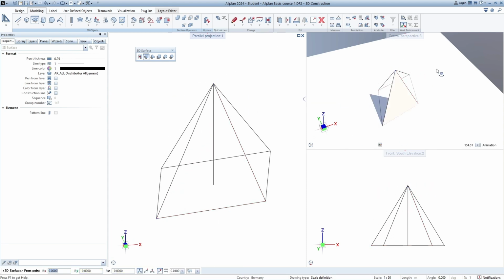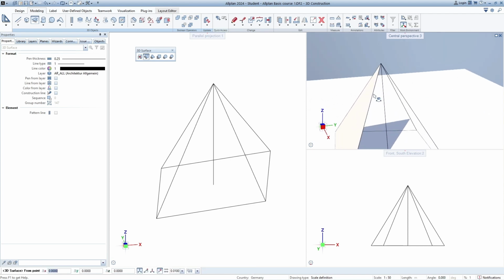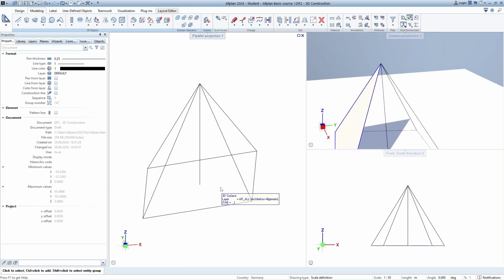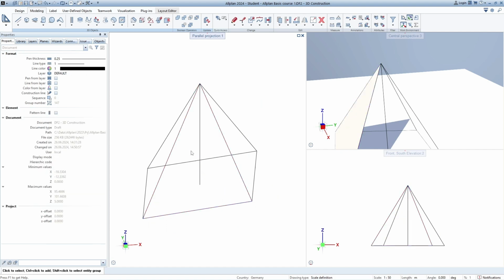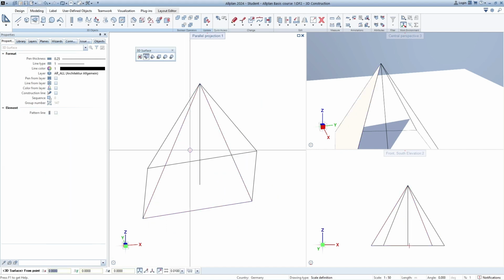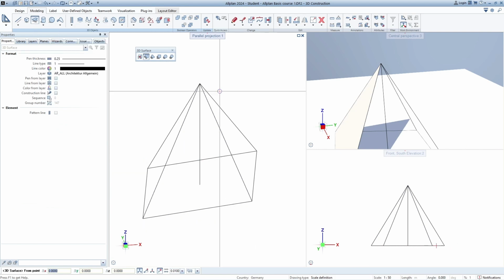And now I can see that there is a 3D surface being generated. Let's go ahead. I just pressed escape a couple of times and we can see as soon as we hover with our mouse over this surface, it can be seen that there is a surface. And as soon as I click on it, I can also see that it will be marked red, which is perfectly fine. So let's do a double right click on the 3D surface, which activates the 3D surface and also takes over all the parameters that are set to this 3D surface.